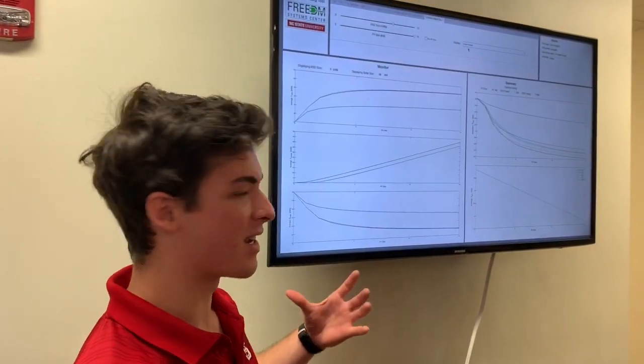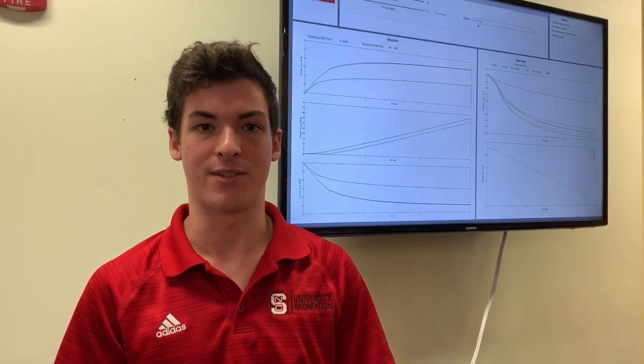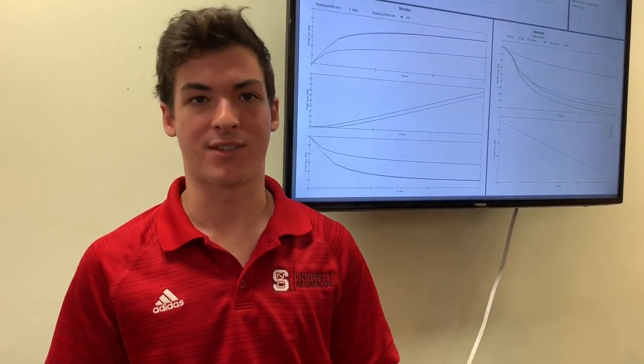Sure. And so on my side, a lot of what I was dealing with was creating a solar array and energy storage sizing tool. And so as you can see, it takes a lot of input on your rate structure, as well as load information for the house that you're sizing PV for, and solar information for that house. And then it runs through thousands of simulations for a variety of solar array sizes and energy storage sizes. And it will provide the optimum size of solar arrays and energy storage that will provide the best financial returns in the future.